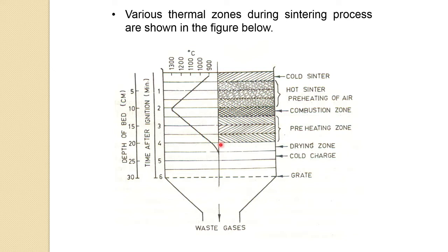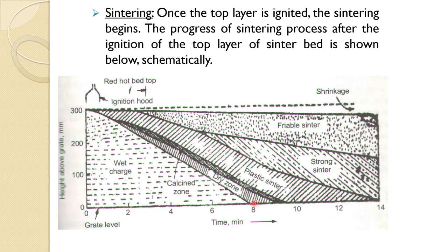And the temperature continuously decreases. What has happened is that this zone is still quite hot, about 400 to 500 degrees Celsius, so moisture evaporation takes place. But once the moisture evaporates, it comes with the gases over here, and the next layer is a cold one. So, recondensation of the moisture occurs here. At one place evaporation is occurring above this, but here recondensation of the moisture is occurring, so the pellet gets quite wet at the bottom, and even water can come out from the bottom through condensation. The temperature drops quite low in this region at the bottom.